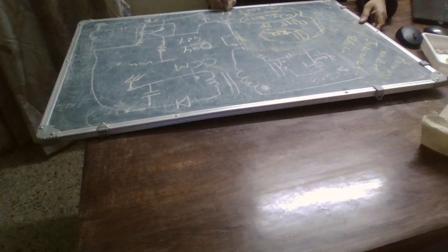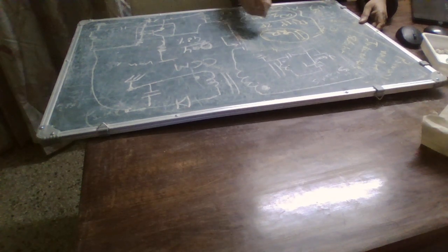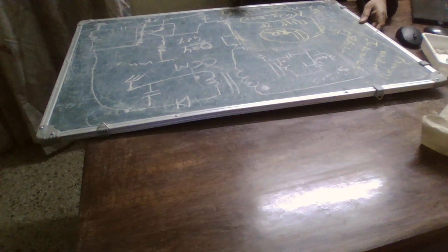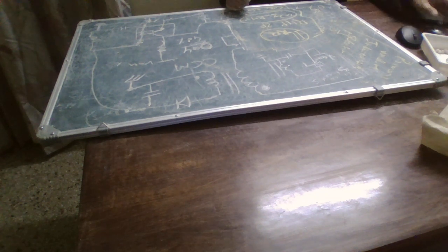subharmonic oscillation. This is much more needed when we are going to use a duty cycle greater than 0.5, because the IC, I have mentioned, can even boost the supply. And if we are going to use a relatively larger inductance value of the primary winding, it is going to result in a smaller falling slope.